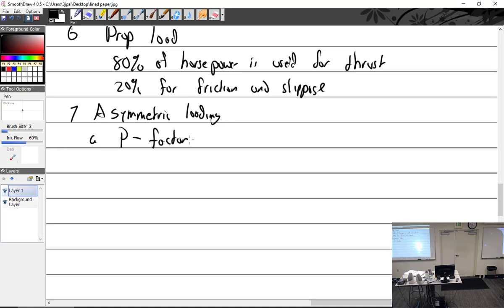All right? But if I were to do like this, now this blade has a whole lot, doesn't it? Can you see which way it's headed off? Not quite 45 degrees. Close. And this one over here is straight up and down. So, straight up and down, not taking much of a bite. Over here, it's taking a lot of bite.